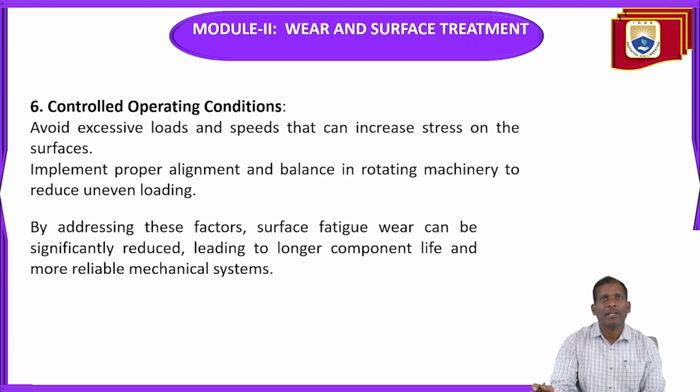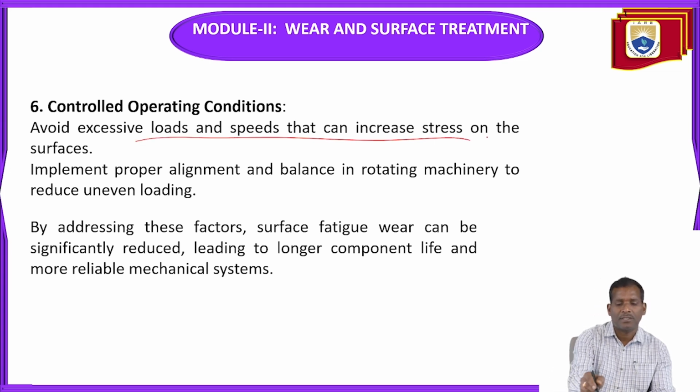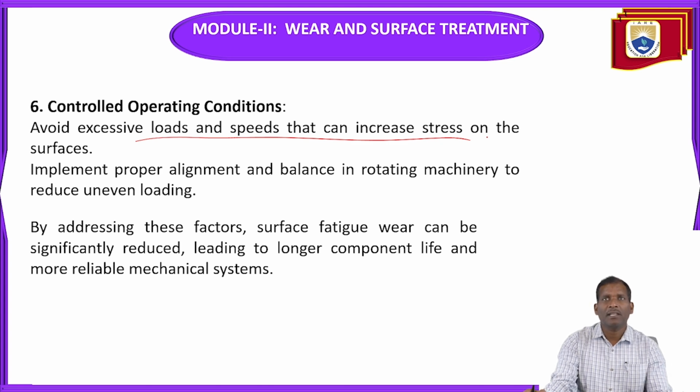Next, controlled operating conditions. Avoid excessive loads and speeds that can increase stress on the surface. Implement proper alignment and balance in rotating machinery to reduce uneven loading.